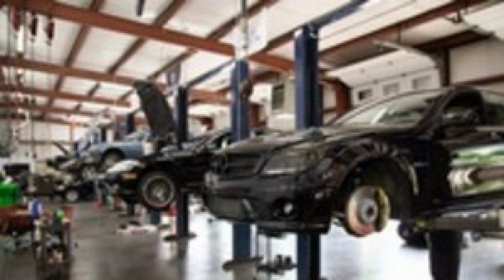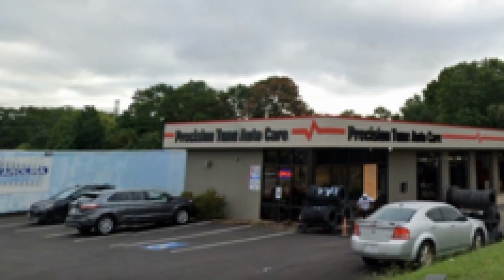Checking the ATF fluid. It is essential that the basic maintenance procedures are followed correctly. The ATF fluid must be clean and free of debris to avoid similar problems in the future. If you can't remember when the transmission was serviced, it is advisable to have the fluid and filter changed. There may be debris in the old oil that is lodged inside. When servicing, make sure you use the correct ATF oil for your specific make and model.